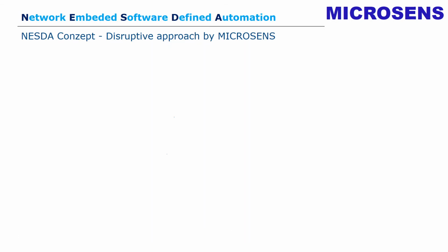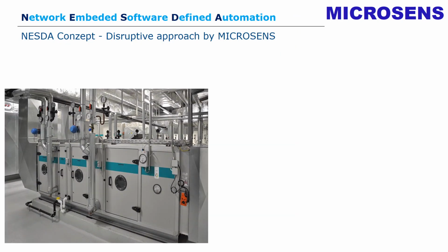So we have again here, for example, our ventilating device. And if you remember, this ventilating device was connected in the first page over a cable tray and conventional cabling to a conventional cabinet. In our approach, we don't do it like this, but we install the smart distribution box directly on the device, like here.